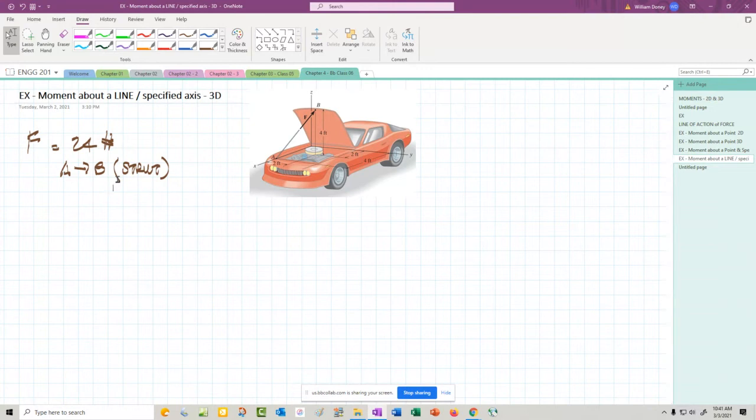Why? Because gravity is trying to moment or rotate the hood down, and we have the force that counters that moment by acting at a distance from the rotation point. So it's really moment of the hood down counteracted by the moment created by the force up. As long as the rod can support it, there's no movement. It doesn't land on your head.